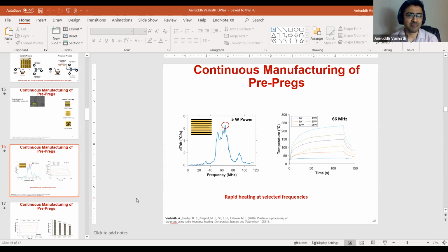really tricky because carbon fibers, their properties are anisotropic. So it also depends. Let's say this is your unidirectional carbon fiber and this is your fringing field. How do you put your carbon fibers over it? Do you put it perpendicular to the field? Do you put them parallel to the field? So these small things also have a really big impact on heating an anisotropic material, and that's where the beauty of simulation actually comes in, where you have to look at what the material properties are.